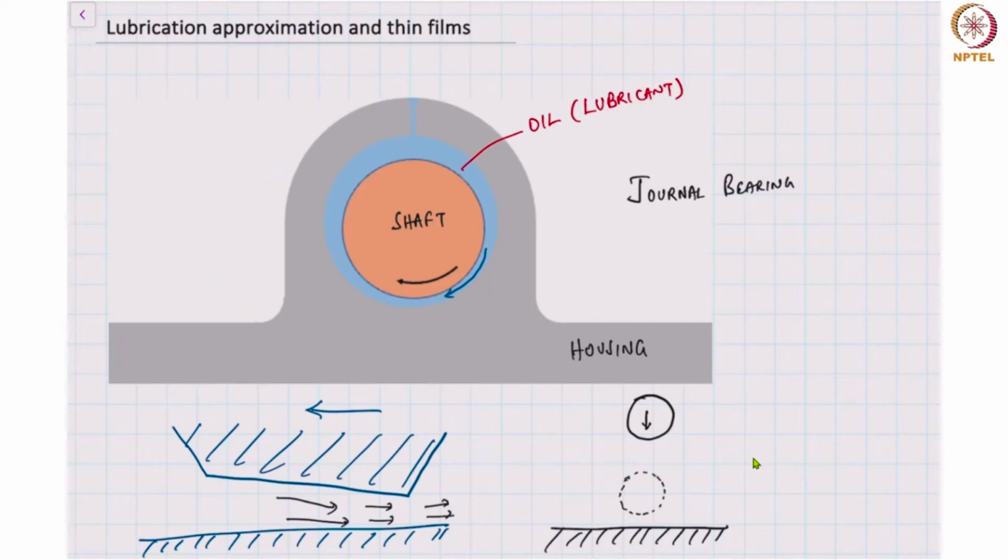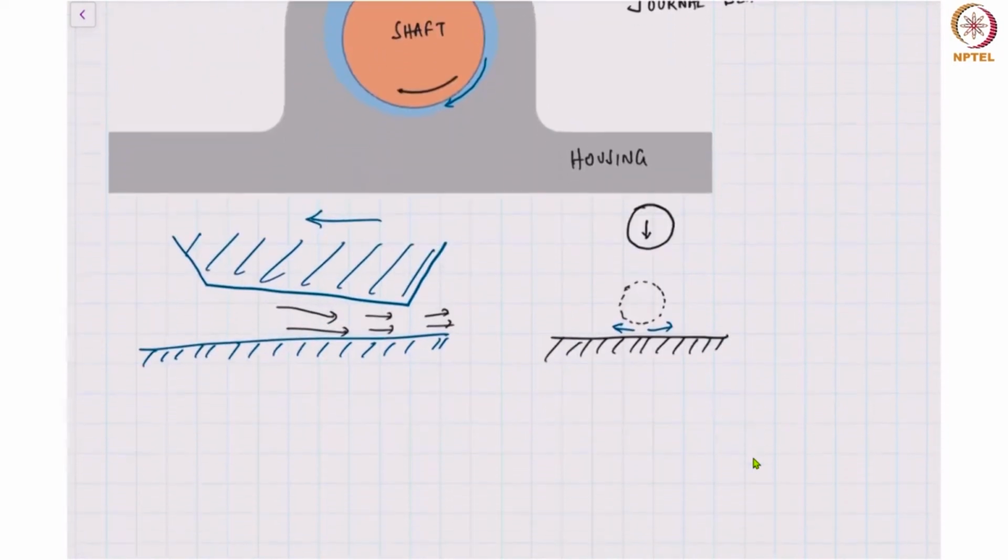The ball is about to touch the surface, and before it makes contact with the surface, the gas around the ball, especially beneath the ball, has to be squeezed out. So sometimes these are also called squeezing flow problems. They all have a common feature, squeezing flow problems and lubrication problems, in that the pressure in the thin gap becomes very large. So the subject of this lecture is what is called the lubrication approximation.